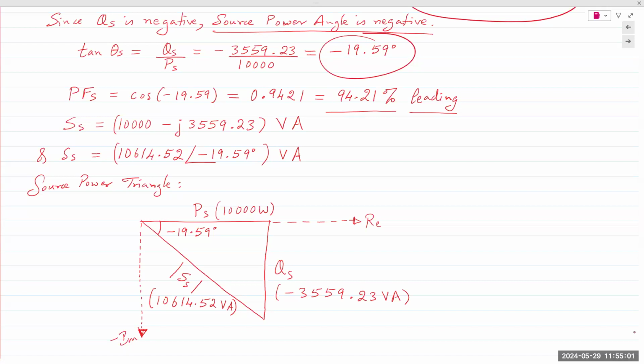You could design a system based on a certain inductive load. But let's say on a certain day, your inductive load drops way down. Then you have to make adjustments to your capacitive load. Otherwise, your capacitor now requires a lot more energy from the source. So companies have to do that, right? Some days if the factory is down or the workshop is down, or the machines are not being run 24/7, perhaps the load is less. So at that point, they have to flip a few switches, depending on the configuration, and disconnect some capacitors from the circuit. Otherwise, now the capacitors are going to require more energy. Make sense?